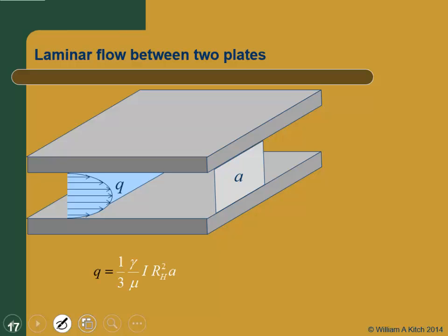If I go back to fluid mechanics, again I'm looking at laminar flow. This is the equation for laminar flow between two parallel plates. And that looks pretty familiar. What's the difference between this and the previous equation for laminar flow in a tube? This is 1/3, the other one was 1/2. Other than that, it's the same thing, right? And that also would be the true velocity that we're talking about. Again, not the seepage velocity, not the apparent, not the Darcian velocity. This is the true velocity.